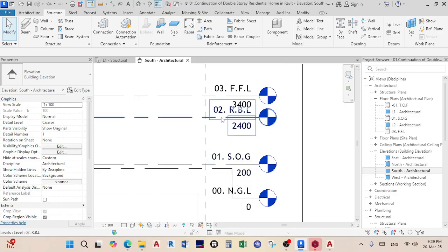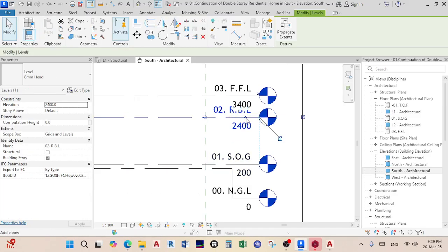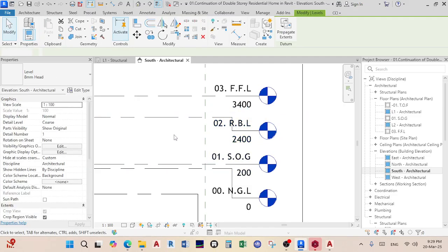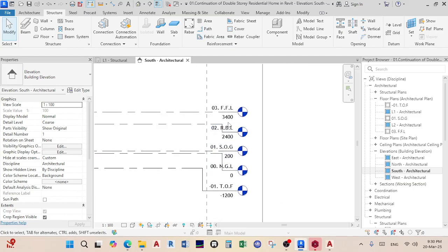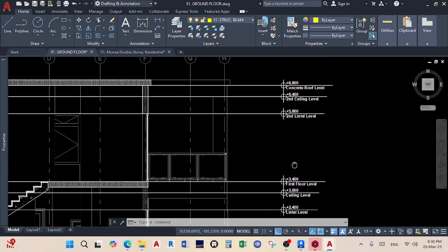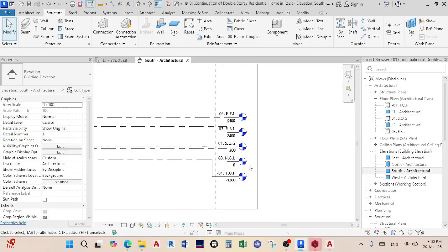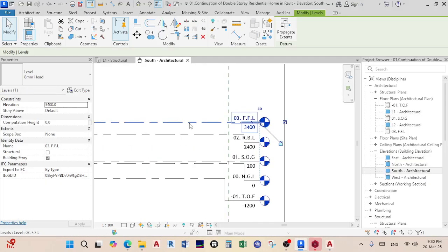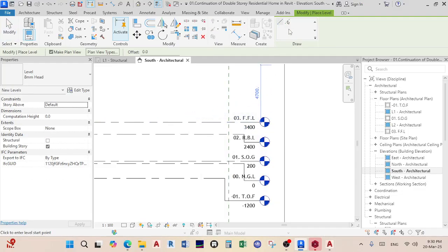Already I'm having that problem there. Things are not in order. I'll just click on that elbow, and then everything will be legible. Now I can read. And then remember, on the first floor, it also has a ring beam for the windows and doors, and it's at 5.8. I'll go into my Revit. I'll select this, right click, say create similar, pick. I give it a difference between 5, what? Was that 5.8 or 5.4?